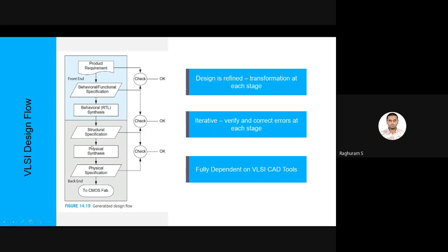So here the front-end VLSI design produces something called a netlist. Again, we'll see this, but the netlist is just a series of gates and interconnections. It has nothing about the size or anything, but that is the starting point for backend, where you see the structural description. So we cannot do with case statements for backend VLSI design.